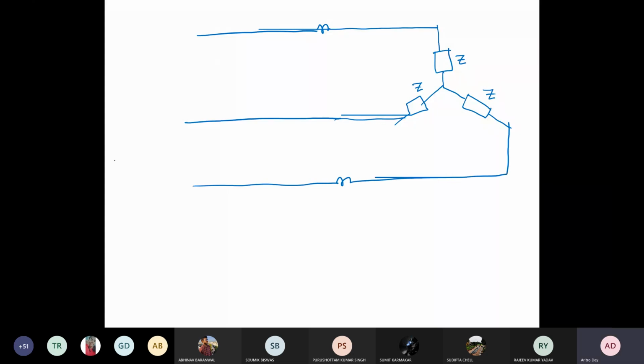And say you have the balanced star connection, I mean supply. So you are using, this is your CC for W2 and this is your CC for W1. Your pressure coil is like this, which you connect between two lines. So if this is A, if this is B, if this is C, between A and C you connect this, your PC.